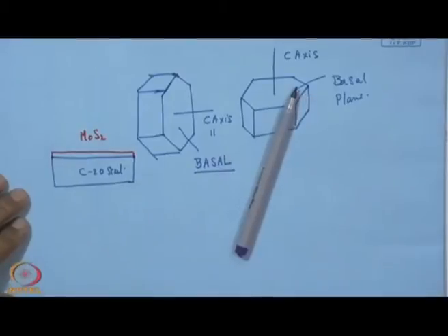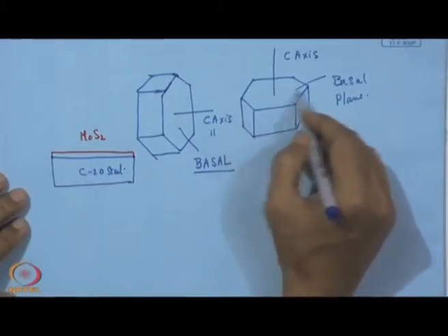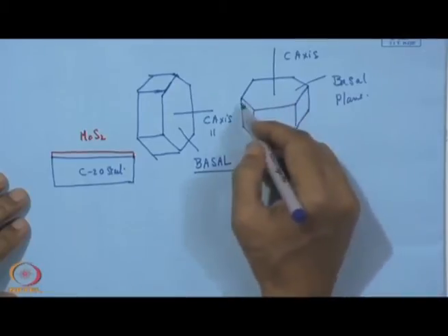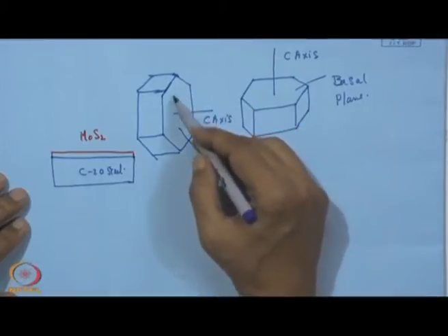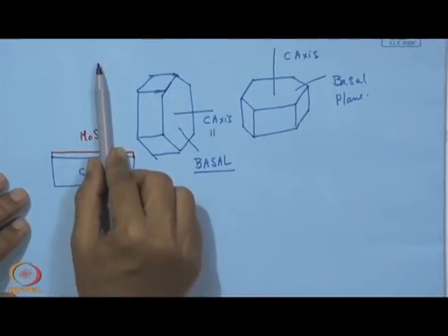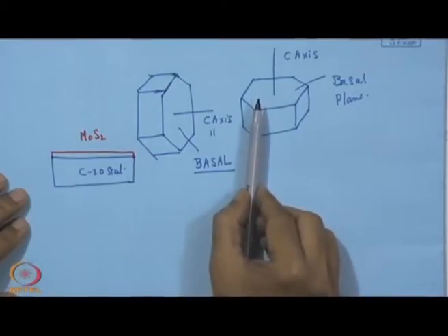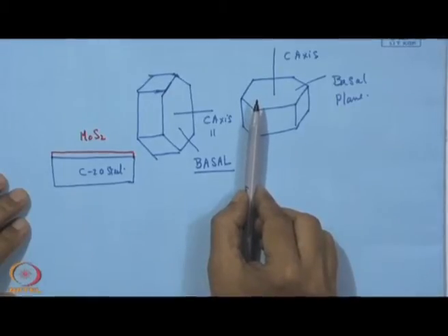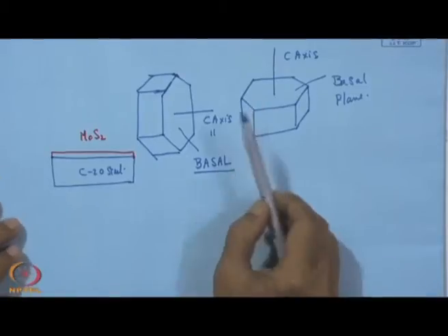So, here we can summarize one thing, that even to have this coating, whether it is PVD or any other process, the first and foremost thing is whether the basal plane is parallel to the substrate surface, because only if it slides in this direction can we expect a good coefficient of friction. If it is perpendicular like this, then sliding will not be easy, rather it will be difficult, with the result of a high value of friction, high sliding force and removal of the coating.